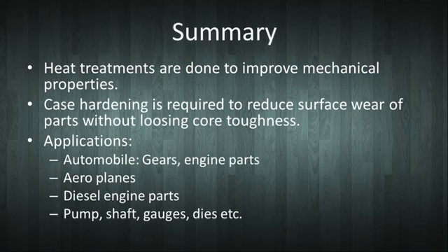Summary: heat treatments are done to improve mechanical properties like ductility, toughness, etc. Case hardening is required to reduce surface wear of parts without losing core toughness.